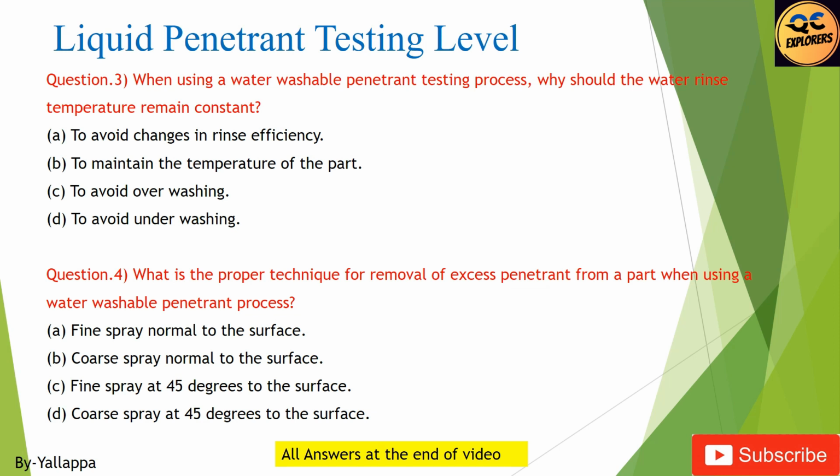Question point 4. What is the proper technique for removal of excess penetrant from a part when using a water-washable penetrant process? Fine spray normal to the surface. Coarse spray normal to the surface. Fine spray at 45 degrees to the surface. Coarse spray at 45 degrees to the surface.